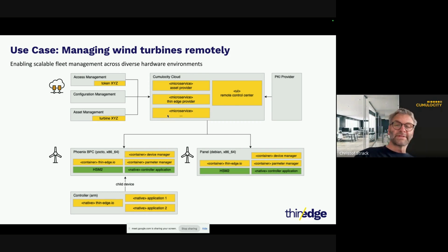and a parameter service then finds out if some action needs to be taken, for example, because the set wind direction and the actual wind direction are too far off. So we need to go to the remote control center and send an information to the turbine to adjust its nacelle to increase efficiency in this case.